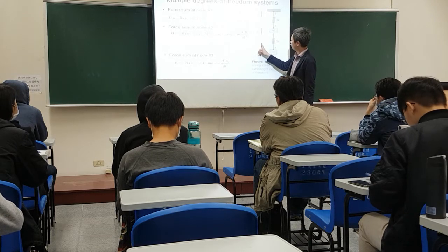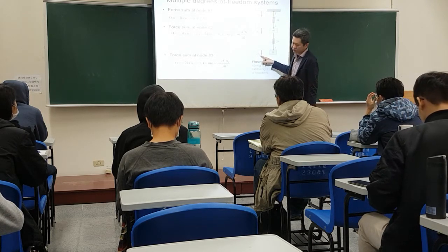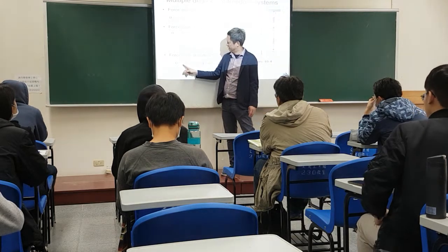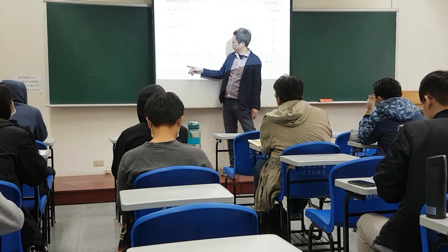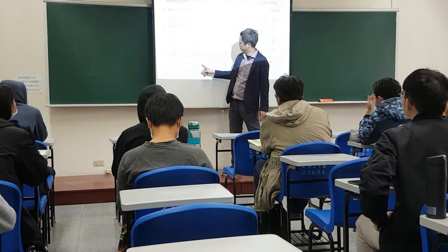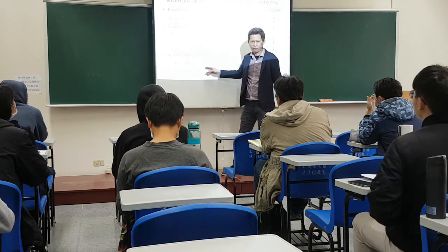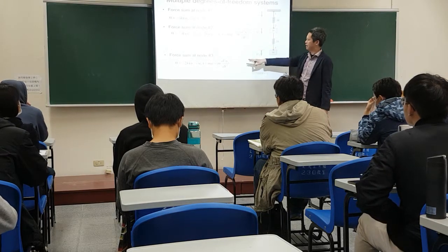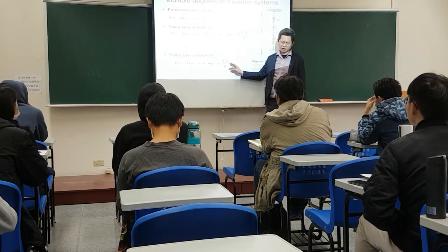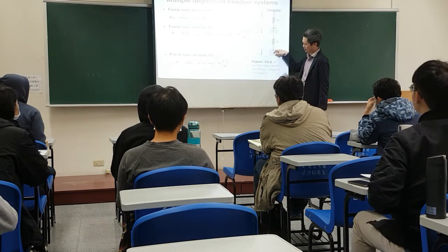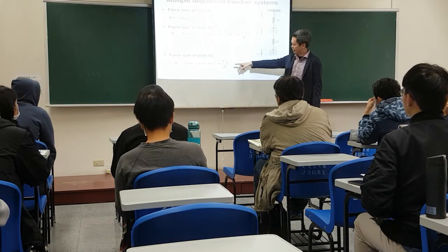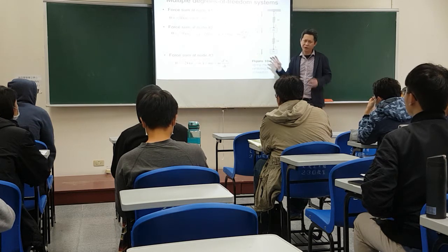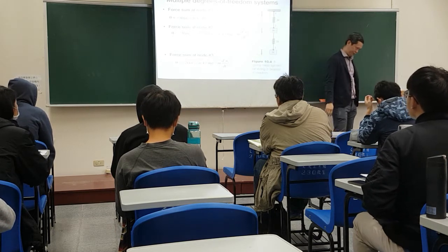See here the third mass. So you have a spring force opposing the downward displacement U3 relative to U2. So that's why we write minus 2k(U3 minus U2). This is the spring force coming from this lower spring. And then minus away the inertial force. When you have the mass accelerating upward, then your inertial force is going to be upward when you are writing in the force balance form.